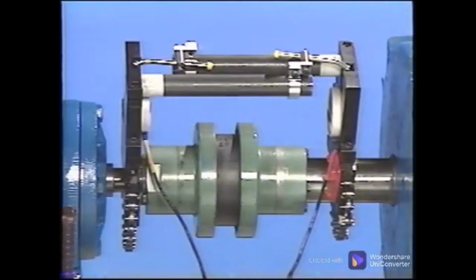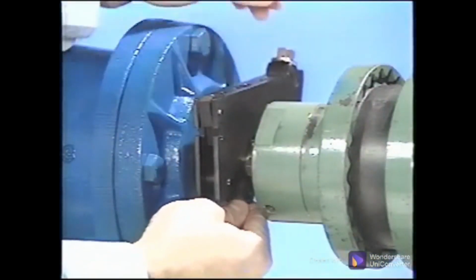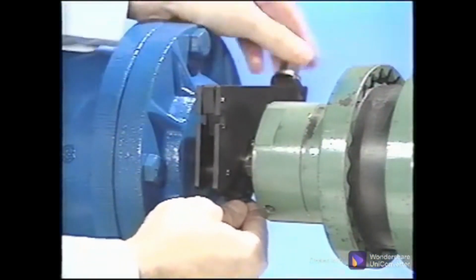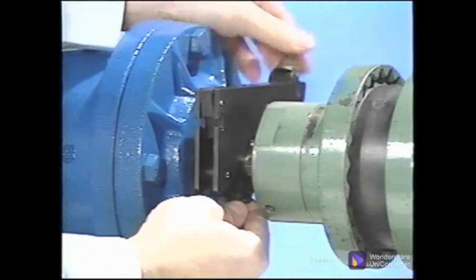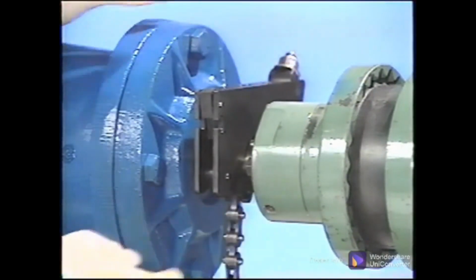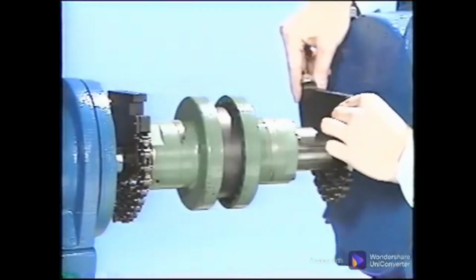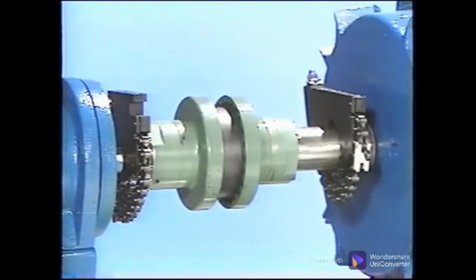In the electromechanical system, the indicators are the digital indicators and are referred to as heads. These electronic heads transfer data measurements from the 4 90-degree positions to an alignment analyzer, which then calculates the moves for each foot. The brackets for attaching the heads must be mounted to the shaft or coupling and require a surface of at least 3/4 inches wide. The farther apart these heads are spaced, the more accurate the calculations will be.